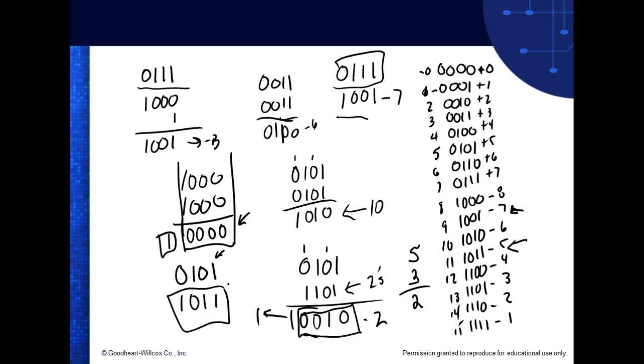So you're trying to do 1, 2, 4, 8 for your negative numbers, and you can't do that. All you have to do is write down the plus number, then bring down the least significant bit, and invert everything else. Yeah, that's exactly right. Most people who've been in binary try to do that 1, 2, 4, 8 code and add them up, but this is a negative number, not a positive number. And we represent it in something we call 2's complement.